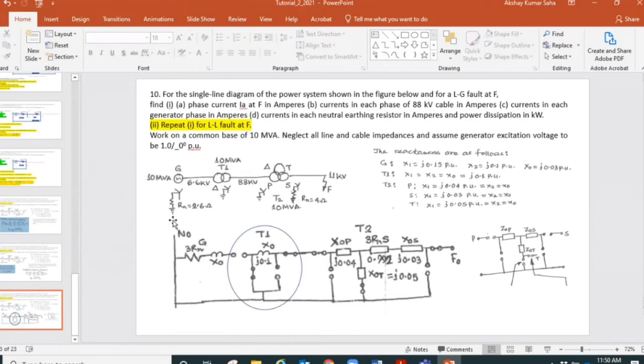Oh, okay, I see, sir. Yeah, so I avoided showing an extra open, because it's already closed. I could see it from the diagram of the power system, star connected and grounded. So that opening is already closed, and this opening is 4 switches, 2 in series and 2 in parallel. So I look at the transformer connection delta, so the shunt switch is closed, and this side is star connected grounded, so the series switch is closed. Done with the transformer. Now we can go to the 3 winding transformer.